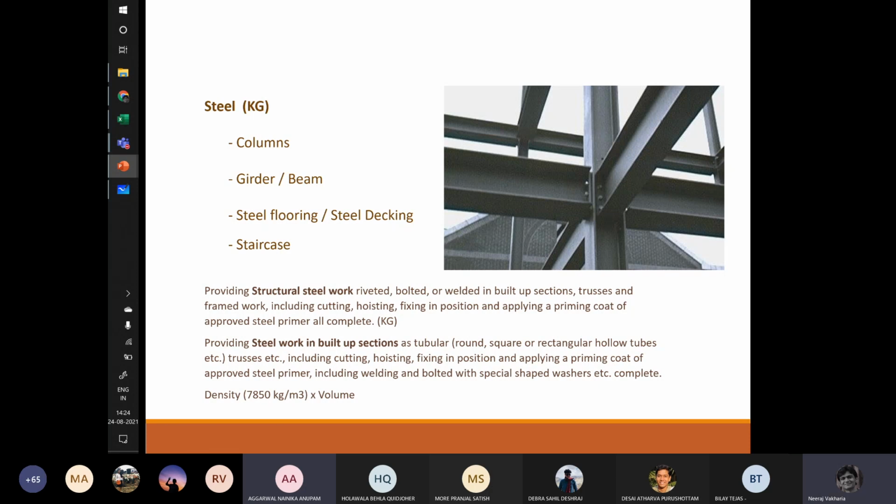Sorry, I had a doubt. Yeah, sure. If we are encasing the steel column with concrete, is that calculation done earlier or afterwards, or do we neglect that? No, we don't neglect that. If we are going to cover it completely, see, when we are covering an I section, then the major chunk of the portion in terms of volume is going to be concrete. So you have to calculate it, but that concrete might not be RCC, like the grade which we require for taking the compressive strength. If I'm just using it to encase the steel column, I might not use M20, I might use M15.